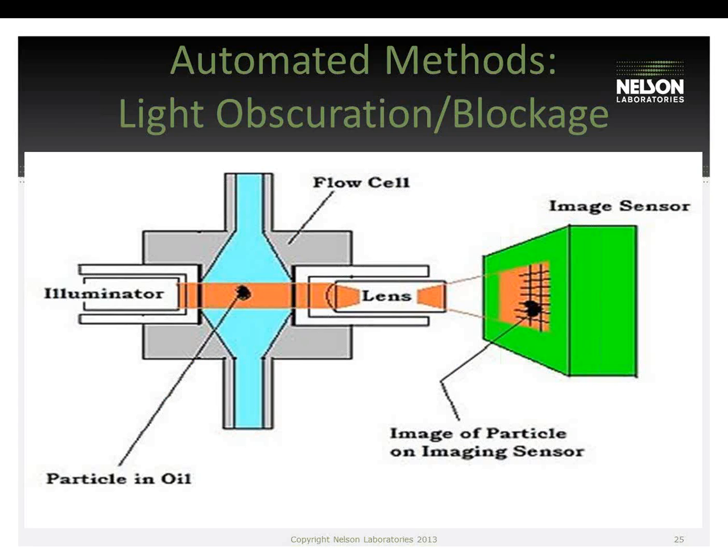Nowadays, light obscuration, the light blockage principle, is the primary mode whereby the automated method is carried out. It may seem rather simple on this diagram. It's an engineering marvel, but really there isn't much to it. There's a microcell or a chamber whereby fluid, whether that be fluid from some type of extraction or fluid from a pharmaceutical product, may be drawn up. As that fluid is drawn up, usually by vacuum, an illuminator shines through the fluid and projects an image on a sensor. That sensor can accurately enumerate and size that particle.